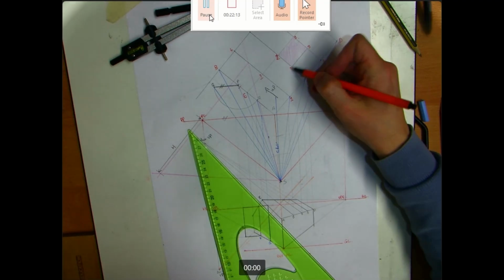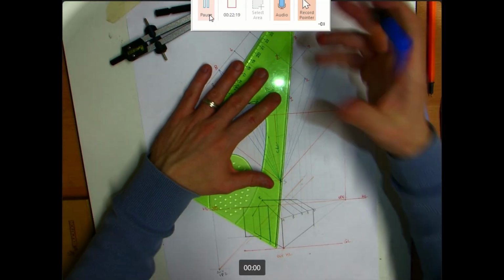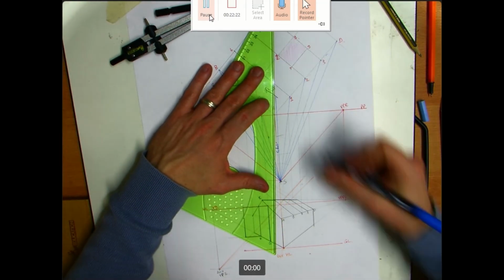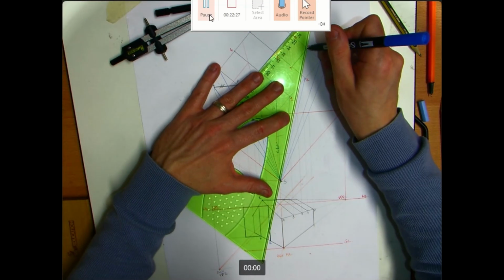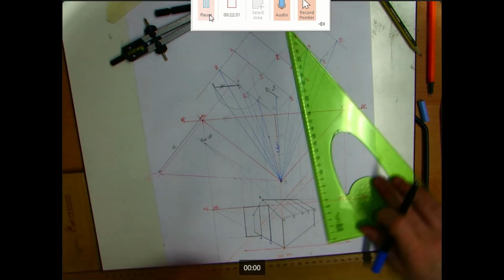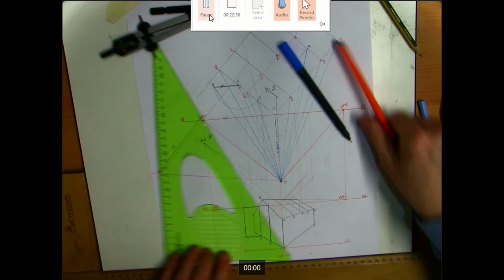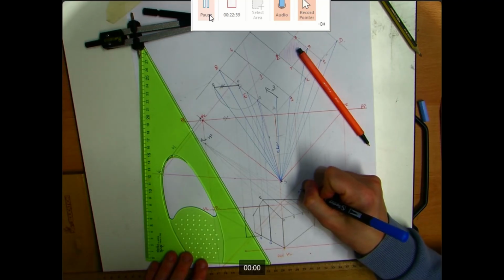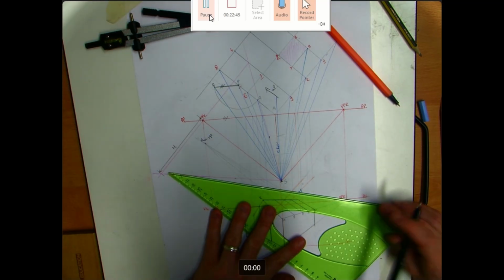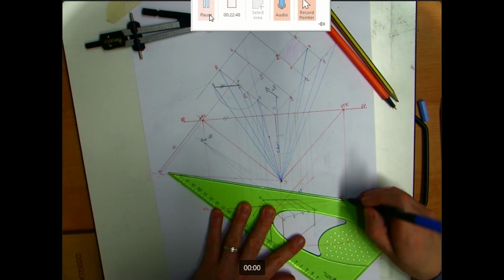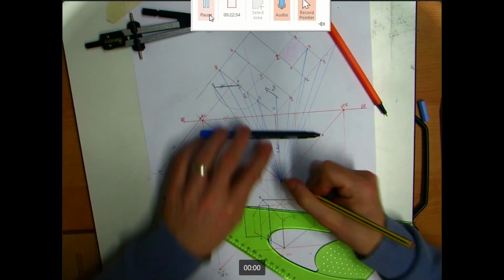And then we're going to need to find out where does that window stop. So, if I take either T or S and I find its location in my front elevation or my perspective view, I can then join through VPR as TS is parallel to VPR. So if I take S to the eye of the spectator, where it hits our picture plane, down in orange, giving us this point here for S. And if I join that through VPR, it should then give me TS.